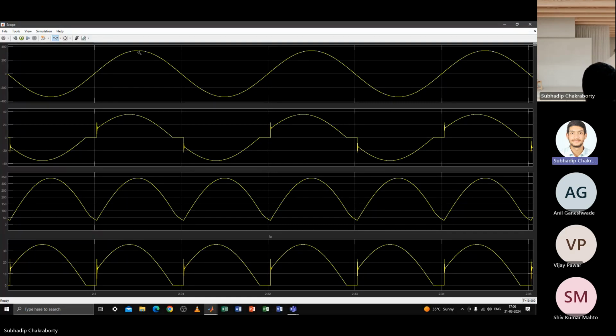So what can you comment about the power factor? The power factor, as I told, and I am repeating, is comprised of two terms. One is the distortion factor, another is the displacement power factor. Displacement power factor is related to the phase shift between the fundamentals of the voltage and current. And the distortion factor is the measure of the harmonic content of the signal. Okay.